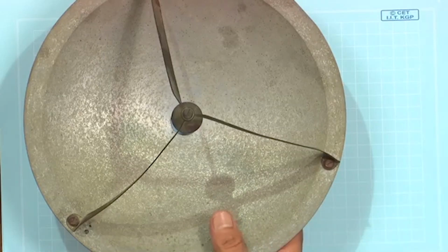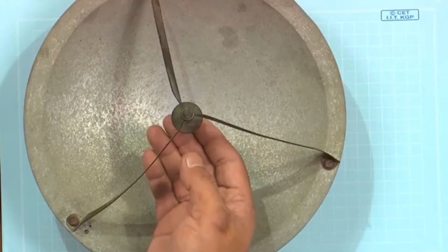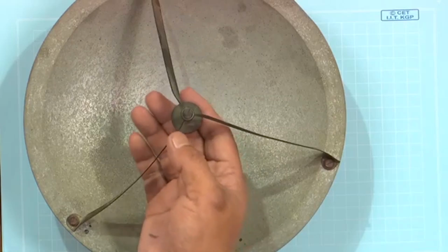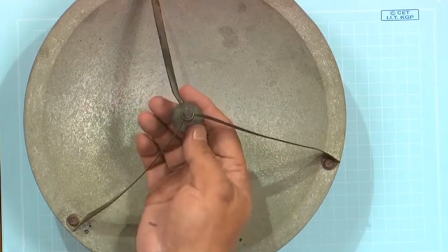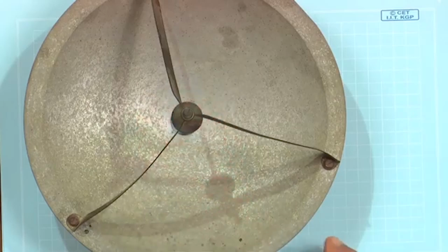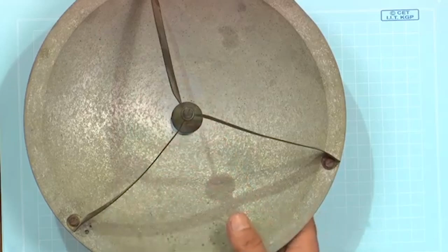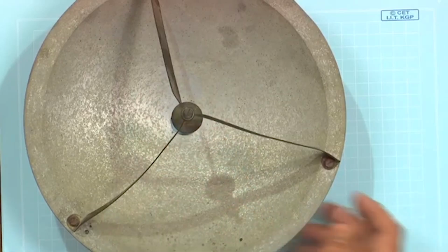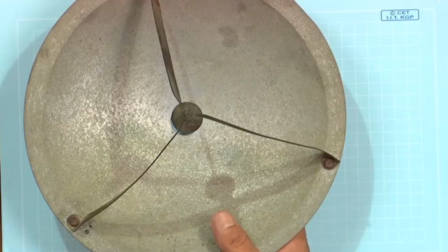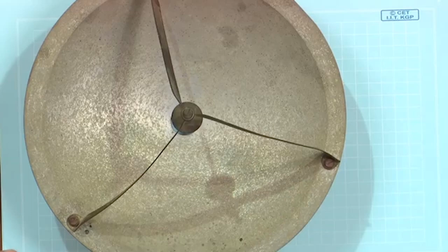So, that is why they do not go for this single feed system, sorry, not single reflector, single feed. Various choices are there, single feed and single reflector, etc. Their choice is the dual reflector antenna system. Actually, this type of feed, which is the classical feed, is called prime feed or front fed feed. So, the feed is in front of the reflector.